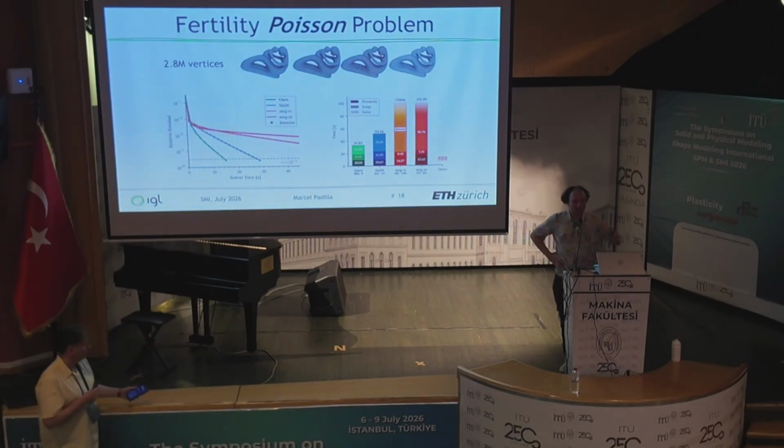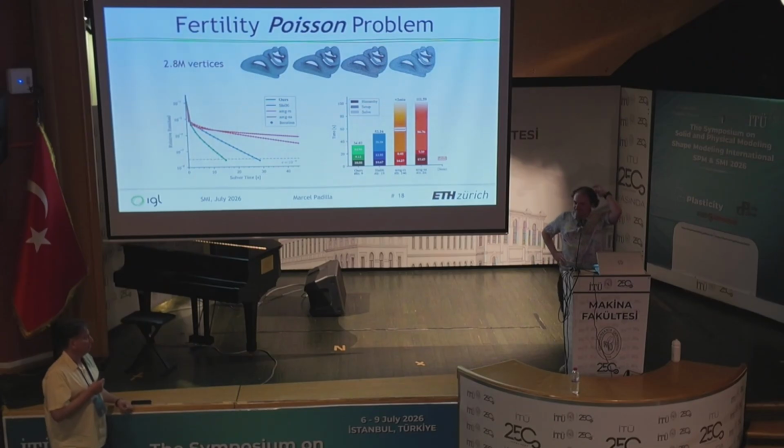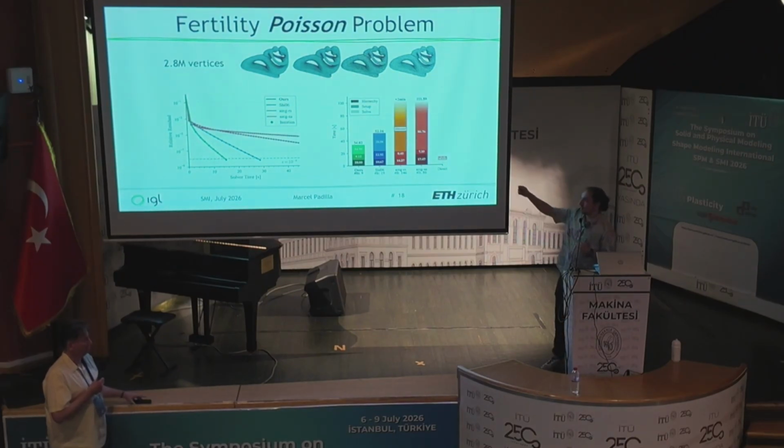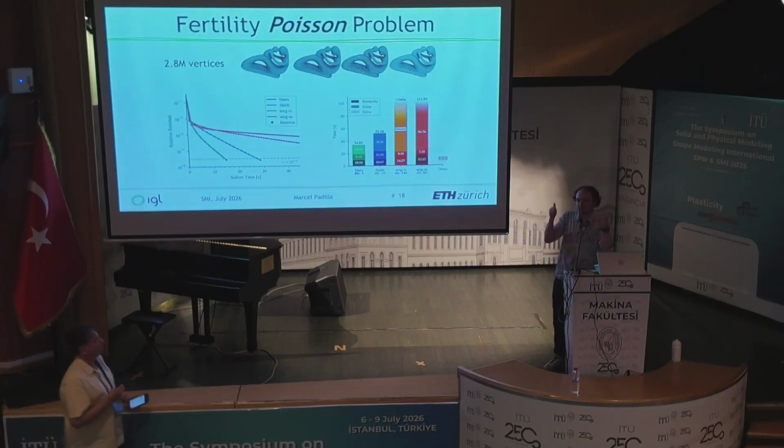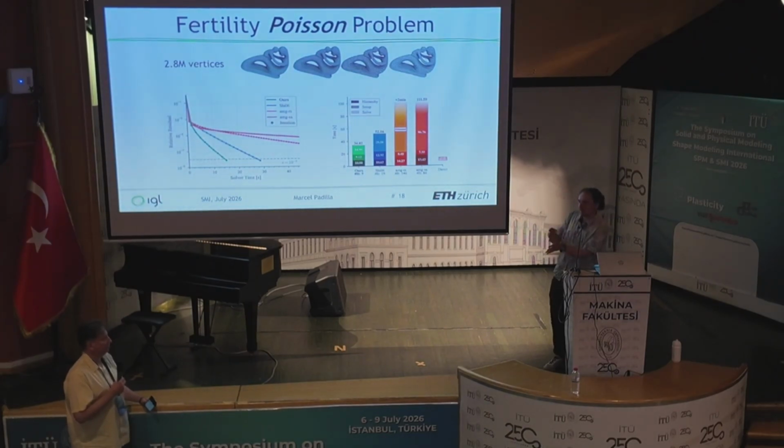Good question. That actually was a problem in the paper. We had an input mesh that we wanted to run through TetGen, and the mesh was broken, which I didn't notice. Then the TetGen output was broken, and it didn't converge well, and it took forever. I was like, what is going on here? Then I had to repair the mesh first to make it watertight. But generally, I relied on TetGen to get these high resolution meshes, and trying to add some noise without inverting something was not the data.